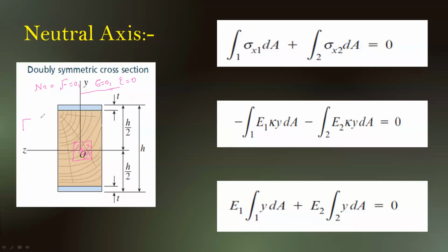So you are having a beam portion essentially like this. This is the beam. And this is a section out of it, a sectional view of this beam. So if you look at this section, you'll be having some value of stress here, sigma, somewhere compressive, somewhere tensile. So on this small area dA, the value of the force acting will be sigma dA. Sigma is the resultant stress, because of two sections.